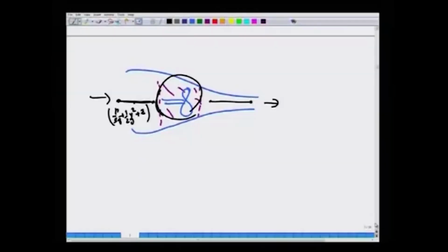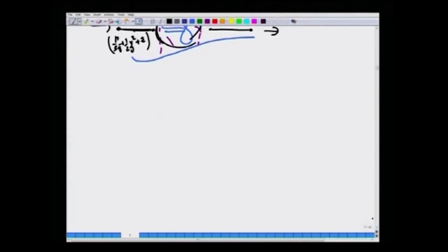And you should know when to apply the classical Bernoulli equation and when to apply the integral energy balance. The integral energy balance is certainly more general in that it accounts for viscous losses, and it also accounts for shaft work contributions either in or out of the CV, okay. Whereas the Bernoulli equation of course cannot take into account all these complications, okay. Now, this is really what I want to say about the integral energy balance. Now, we have to apply this integral energy balance to some specific context, okay. The context which I am going to discuss first is flow measurement.